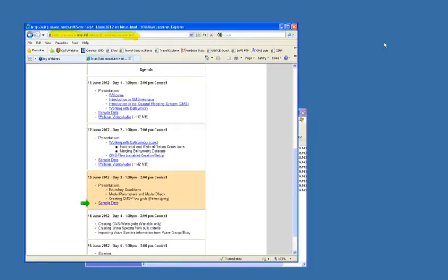So we brought in our bathymetry, and then we started working to build our actual conceptual model. And if you save your project periodically after your model's already been conceptualized in the map data, we loaded a coverage, that information will actually be stored in a file called whatever name you give it, .map. And you can always load that back in and have access to that again.